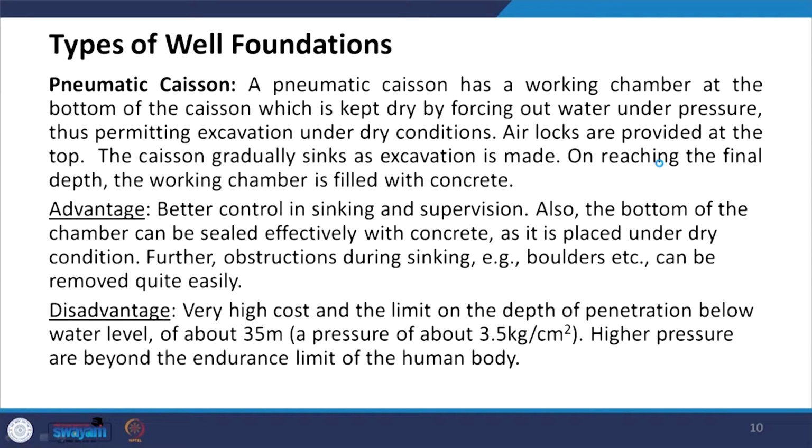So, once it is filled and has reached the final depth, this can be filled with the concrete. So, this is the advantage of pneumatic caissons: better control in sinking and supervision. Also, the bottom of the chamber can be sealed effectively with concrete as it is placed under dry condition. Further, obstructions during sinking, for example boulders etc., can be removed quite easily.